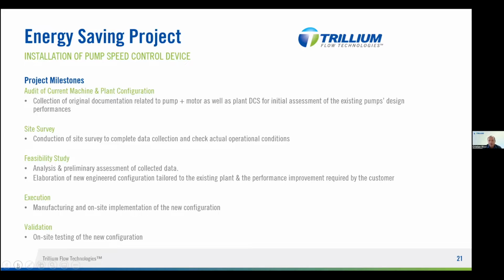In general, what are the project milestones from the beginning, from the first study up to the execution and validation of this solution. The first point, of course, is to deal with the end user in order to understand from them the current situation of the plant. So we are going to look through the documentation of pumps and motor. We are going to look at the DCS data of the client in order to understand the current working point of the plant versus the pump design performances.